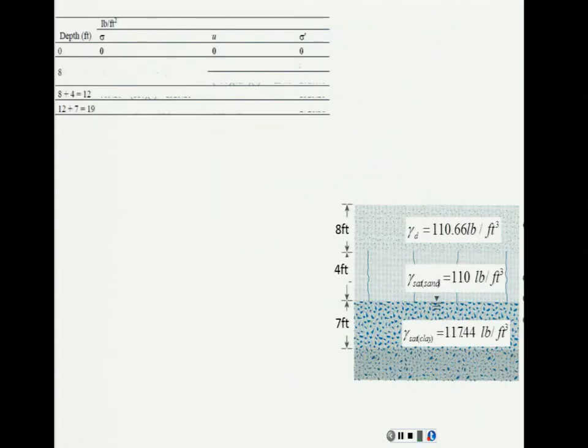So that's why you have in this equation the 50% of gamma of the water times this 4, and that's negative. 50% times this 4 times gamma of the water, that's a negative pressure. That means that if you look closely now, when I subtract this minus this, basically I'm adding this value. And that's important because in the zone of capillary rise, the effective stress is increased.